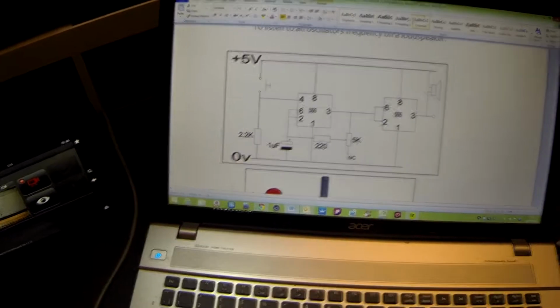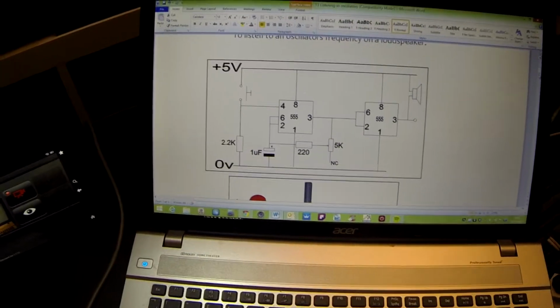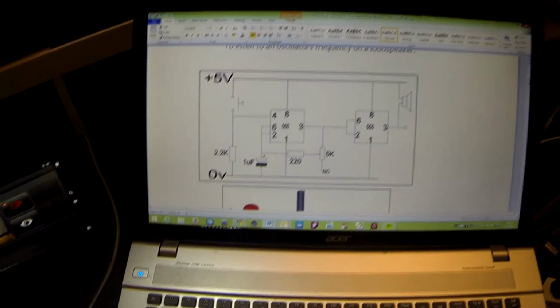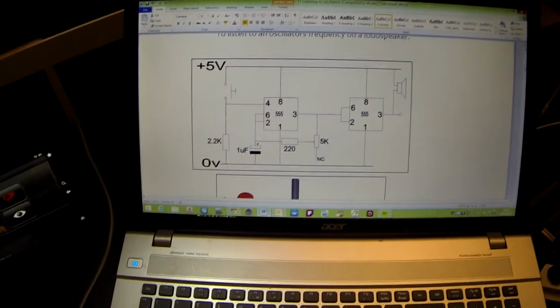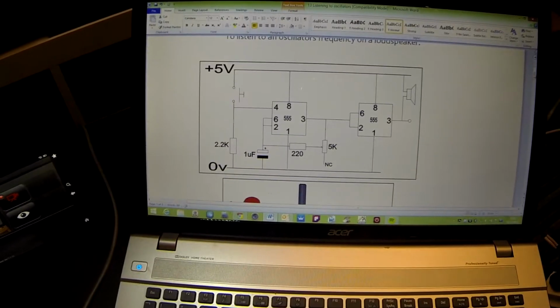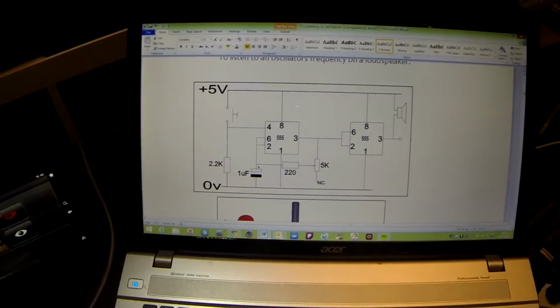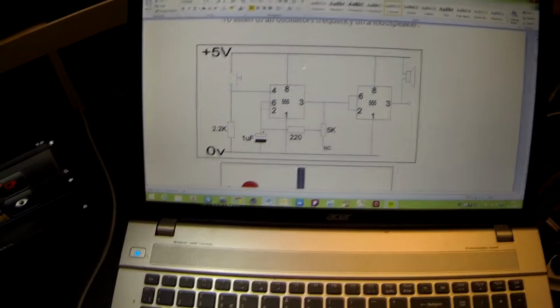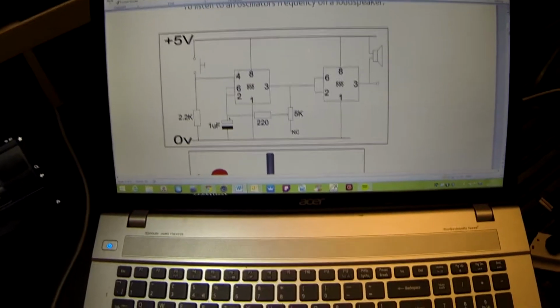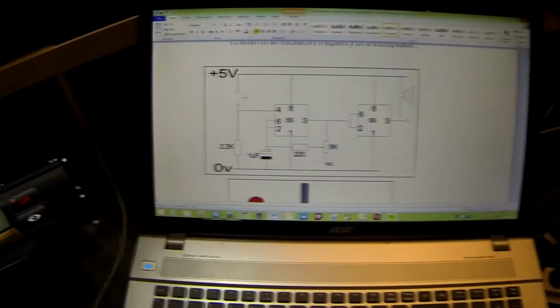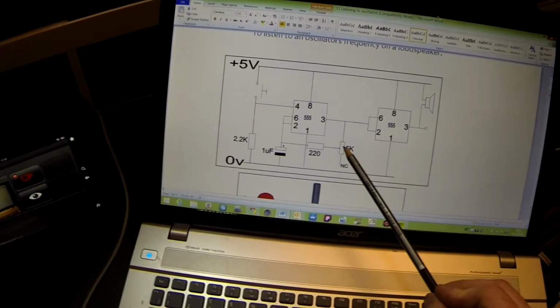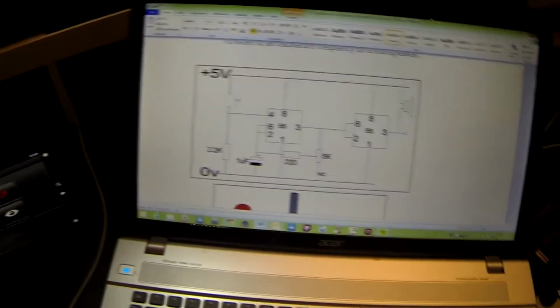Light devices, where we have a change in output as light falls on something, the only component that we have met that does this is called the LDR, the light dependent resistor. Therefore, it makes sense that we can replace our resistance in this circuit with an LDR.